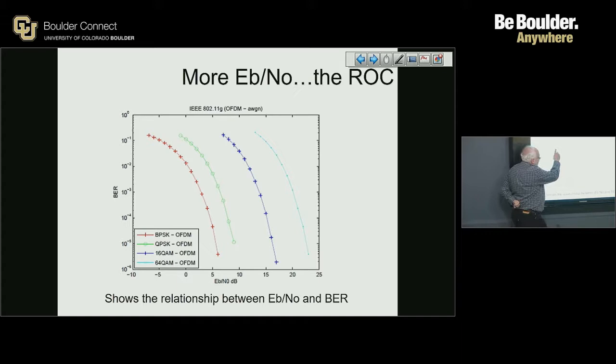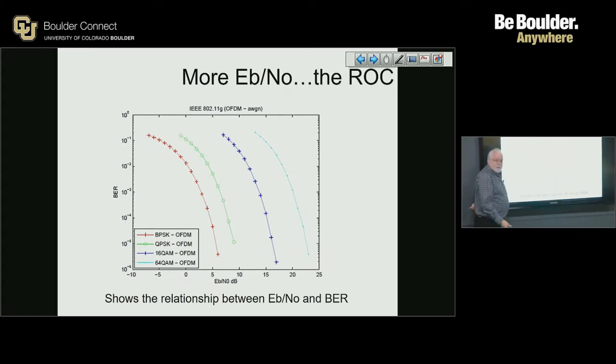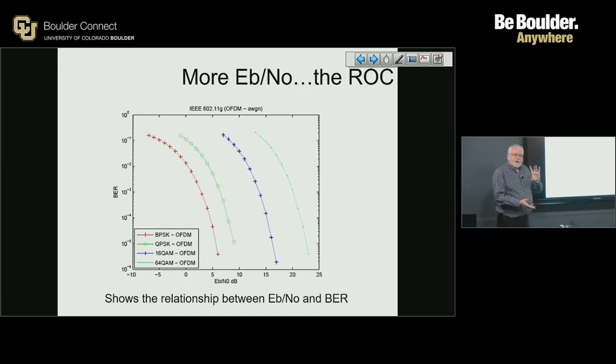You can see that as you increase the signal noise ratio, the bit error rate goes down, as you would expect. If you go back to that eye diagram we looked at the other day, what that says is that as the signal noise ratio increases, the eye opens up wider, so it's much easier to decide where the bit boundaries are, whether it's a 1 or a 0 you're transmitting.